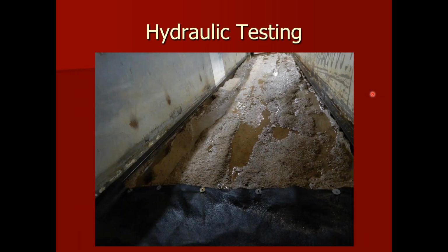Before we made correlations, though, we had to document the soil loss. So you can see typically what we've done in the past is with a point gauge, you go through and try to find the gully and then measure the depth of that gully and then hope you can sort of back that into some average soil loss across your system, or a representative value of soil loss per given shear stress in correlation to what that half-inch threshold would be.